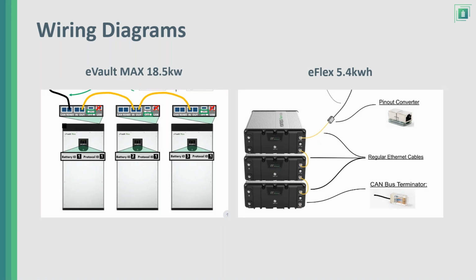And one of the things that we have to make sure of, and remember, this is all because we want to be able to create a closed loop communication between our battery bank and our inverter, is that all the batteries have to be interconnected among each other, so the different BMSs from the different batteries will be talking to each other. I'm trying to show here how this interconnection occurs.